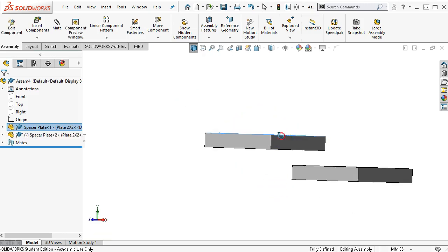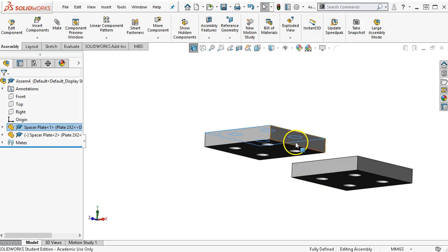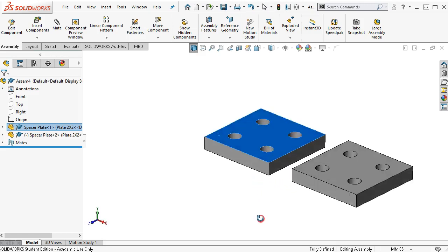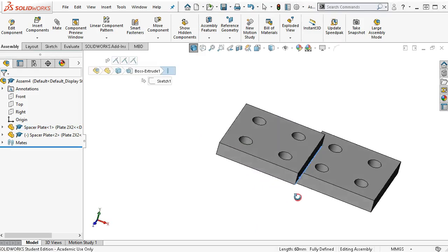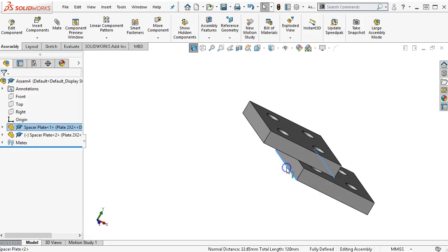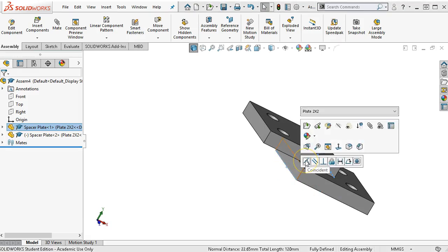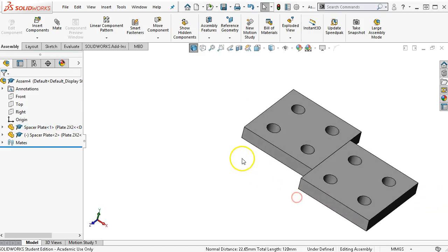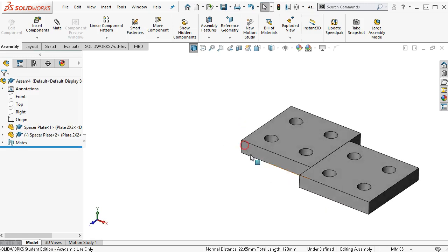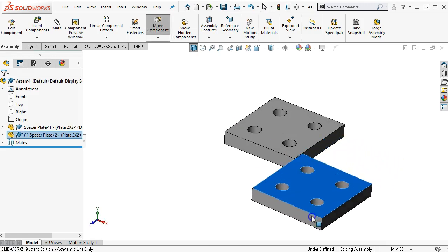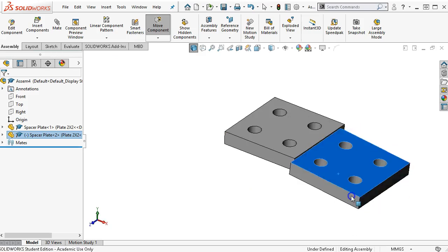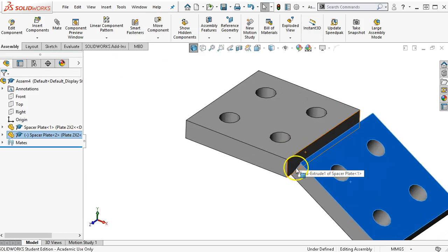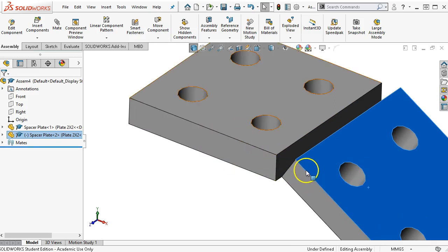Alright, so my natural tendency would be to go face to face, face to the back of that, and then face to face, something along those lines. That gives me the best, most stable geometry. When I've gone edge to edge, there have been not too many issues, but occasionally there are issues. Now on the surface, this is able to rotate and move back and forth, and so with the faces, I'm having to select 3 faces.